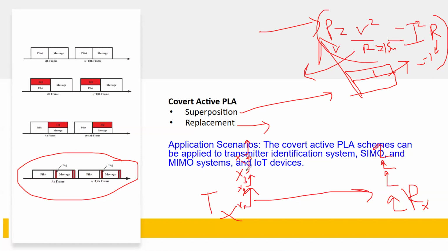If you send different signals, you will increase the data rate, which is the speed of the internet you can think of, but you will increase interference as well as complexity. If you send the same signal from all the antennas, you will increase the reliability of the system and the range, the quality of your signal, but the data rate will not improve. I mean, the speed of the internet. So this is what we call MIMO.